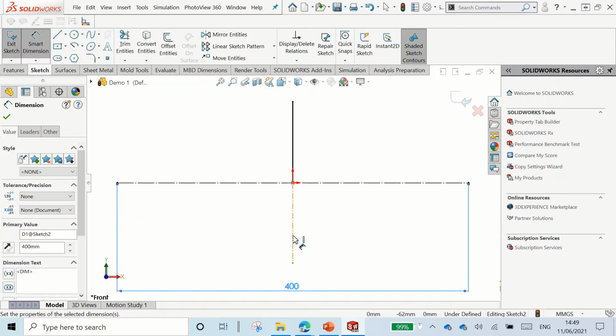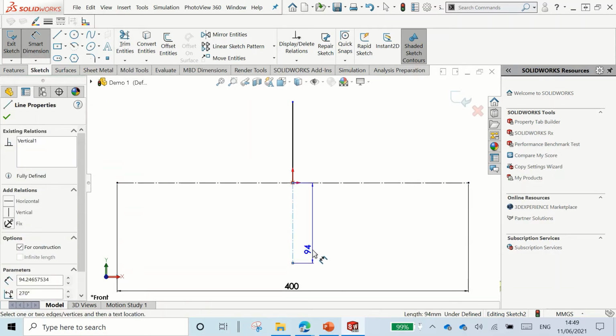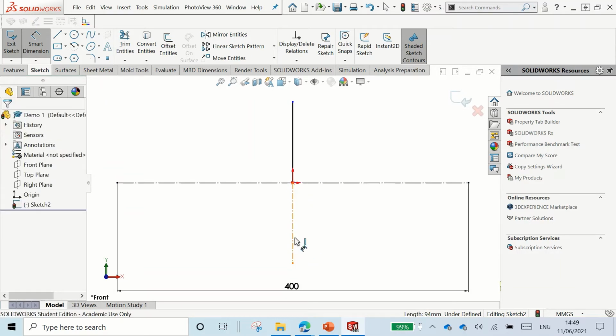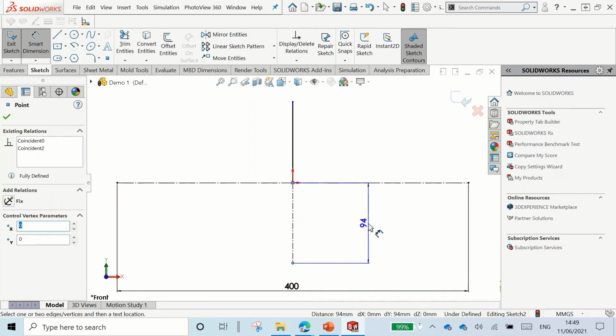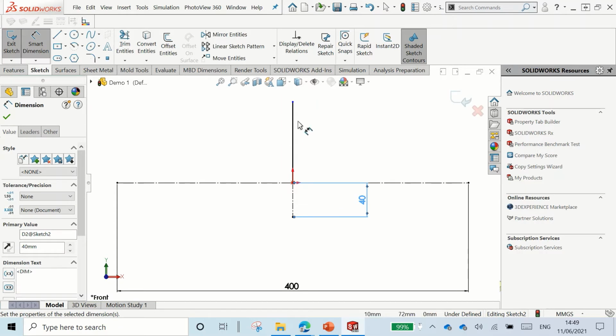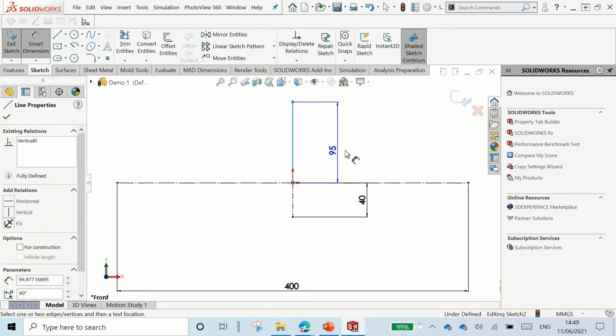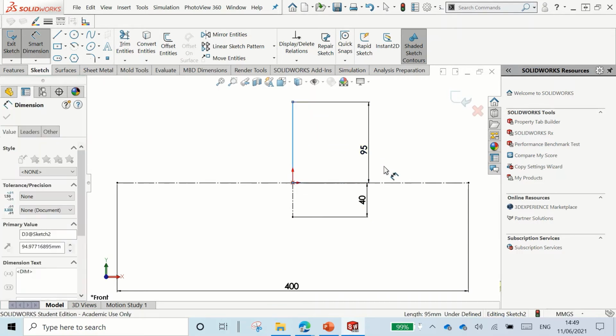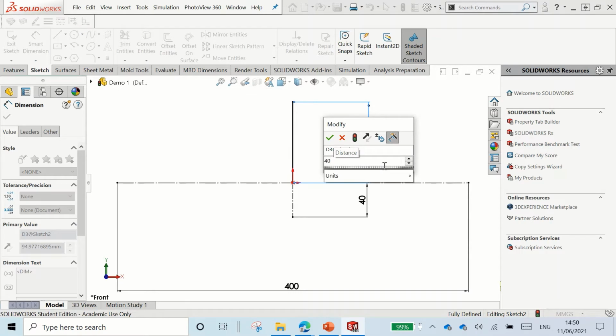So now I want to change the height length of this line here. If it didn't perfectly select just that construction line, I can go point to point and I can go again, drag out, left click, and type in 40, and I can go green tick or enter again. It's the same here. I'm going to select this line. If it doesn't highlight, I can click the top points, drag out, and go 40 mil, like so.